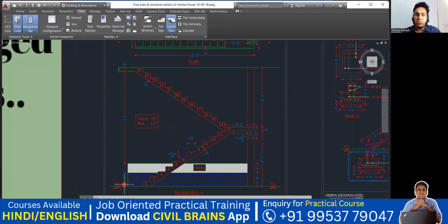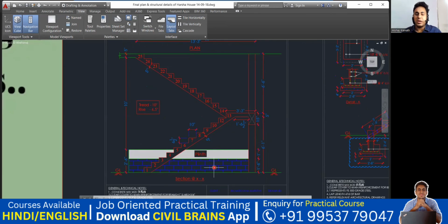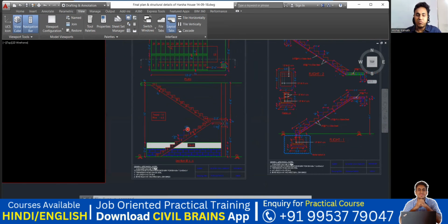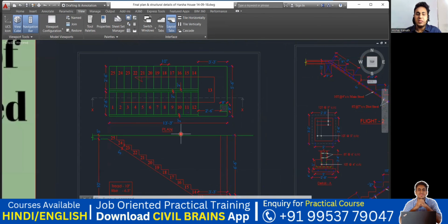So this entire is one floor. This is floor to floor distance. From the bottom of this floor to the top of this floor, it is 10 feet in height. This much is clear. And of course, this is your plinth beam, and over this is your laterite wall. Over that you put a plinth beam, and beside that your staircase will come. Got it? So this was the entire elevation, I mean the section of that, and then this is a plan of that.